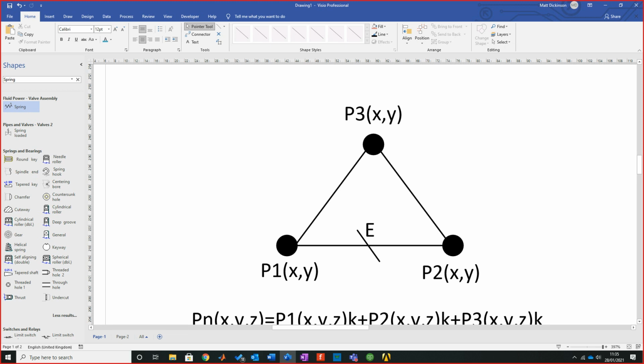What you end up with is a way to be able to do a design, pass it through all the FEA analysis, put it through prototype, and it'd be the most dangerous thing in the world. So depending on what it is, if it's a bracket for a vehicle of any type, and if anybody's used the default mesh, what this actually does is it allows them to pass off a part which is incredibly dangerous, which could lead to death, God forbid, but death. But you've instantly got a point here where it can fail.